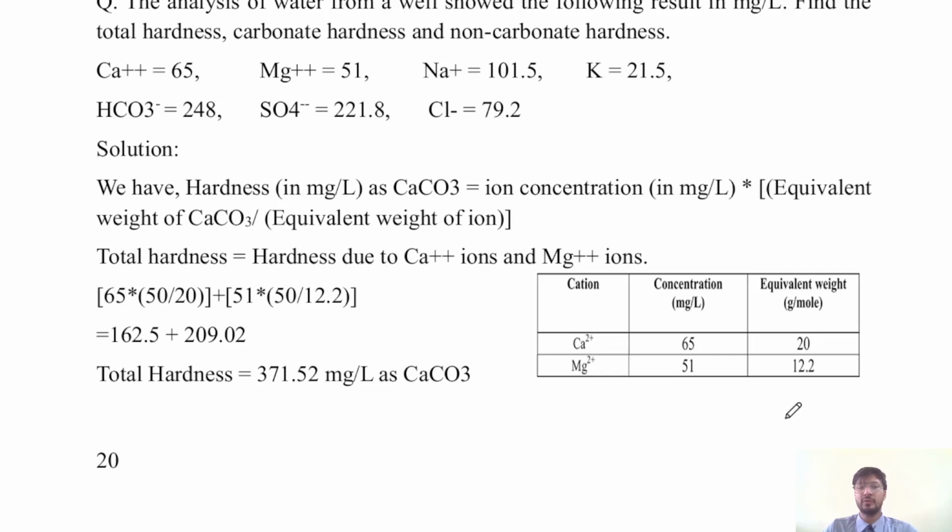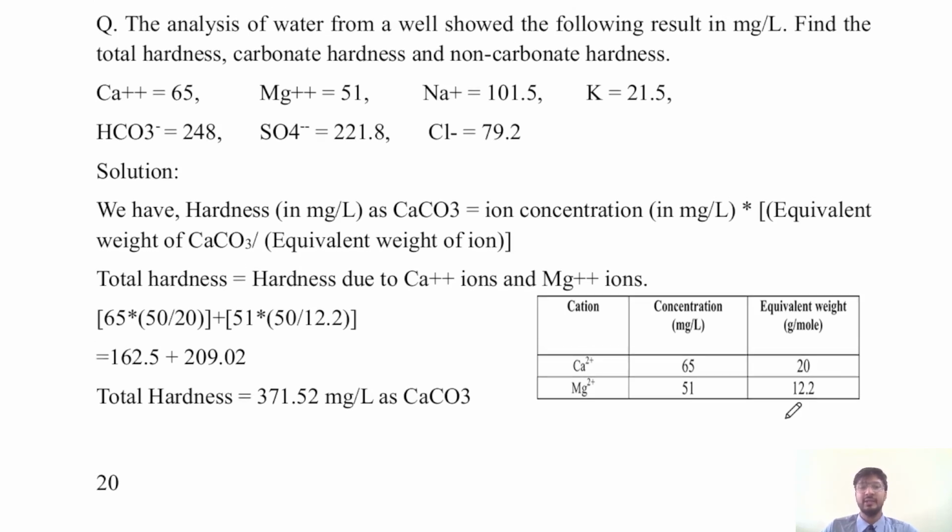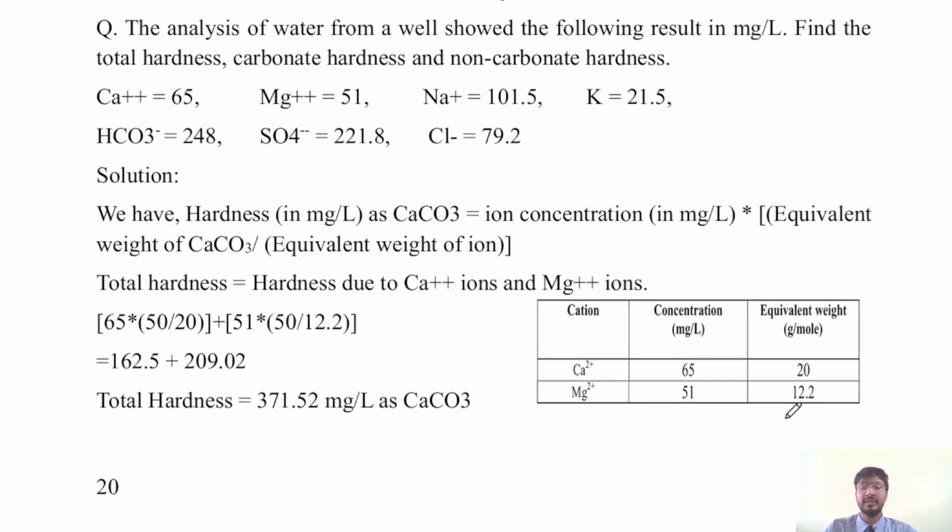When you know both total hardness and total alkalinity, you can decide the treatment process like lime soda versus ion exchange, predict whether the water is scaling or corrosive, and control industrial problems in boilers and cooling systems. So let's now move into a very important and practical segment of today's class, the numericals on hardness and alkalinity, which is frequently asked and used in water treatment planning.